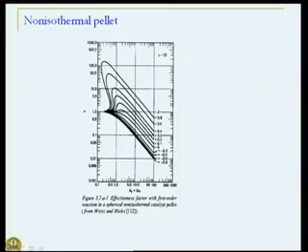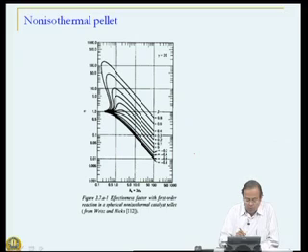But for exothermic reactions, if the temperature is high, even though concentration may be low, the higher temperature may result in rates of reaction inside the catalyst pellet higher than those at bulk condition, and hence the effectiveness factor, which is the measure of our observed rate to the rate at the bulk condition, could be greater than 1. That is one aspect that we had seen in the last session. So, let us look at it one more time.